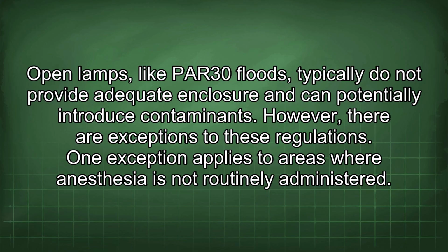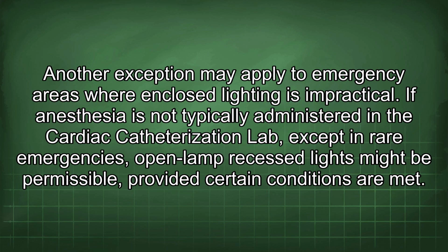However, there are exceptions to these regulations. One exception applies to areas where anesthesia is not routinely administered. Another exception may apply to emergency areas where enclosed lighting is impractical. If anesthesia is not typically administered in the cardiac catheterization lab, except in rare emergencies, open lamp recessed lights might be permissible, provided certain conditions are met.